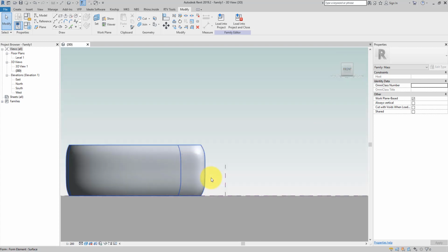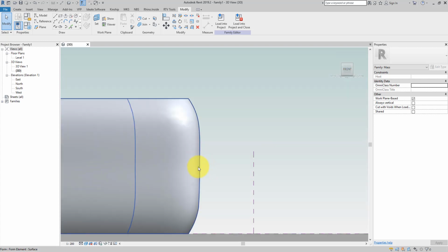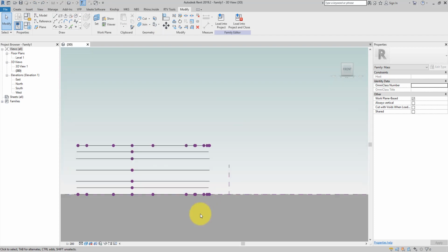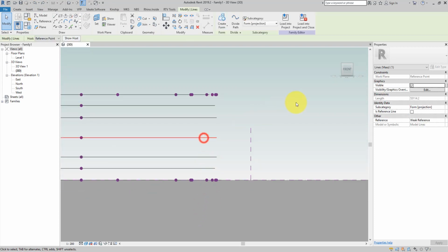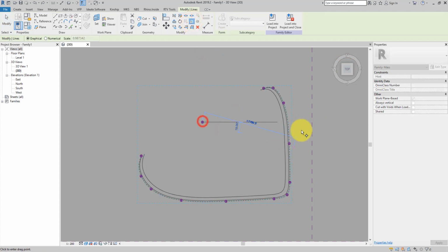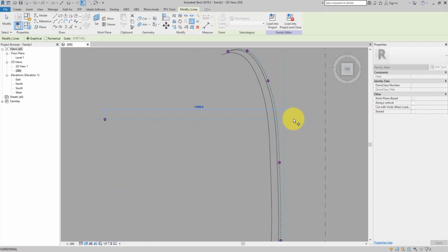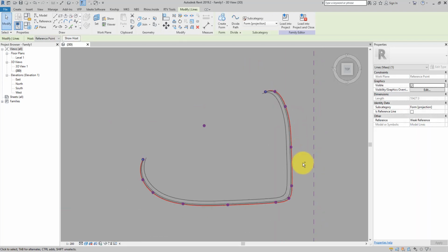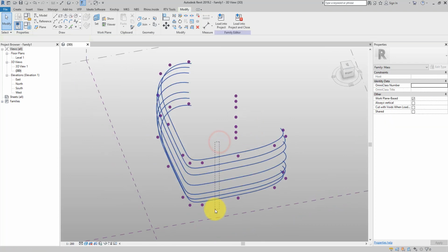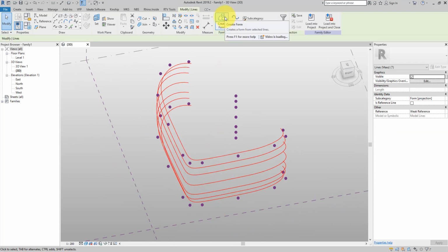Anyway, I can still see that it's going a bit inside, right in the middle there of the surface, so we can fix that now. Let's undo one more time. And then select this middle line. This time I have to bring it forward, so do scale again. This time I'm going to go outwards to make it bigger, like this. Just by a little bit. And now you know what to do. We can now select those lines one more time and do create form.